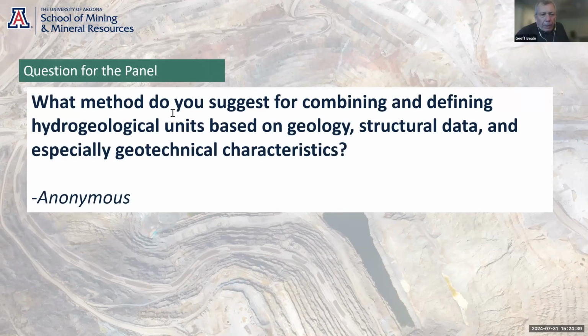Yeah, and then there's also the mining induced side of it. Typically, we define a blast damage zone, which is the zone where you've got mechanical breakage, which may be anything from 10 meters to 40 meters, maybe even more. And then you have the zone of relaxation, which is where the stress relief caused from mining causes dilation and opening of fractures.